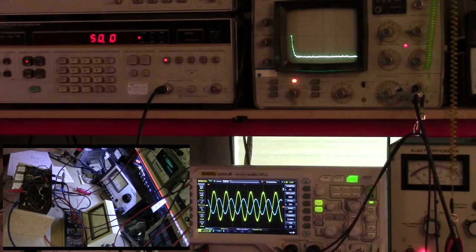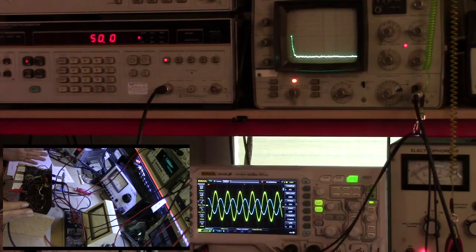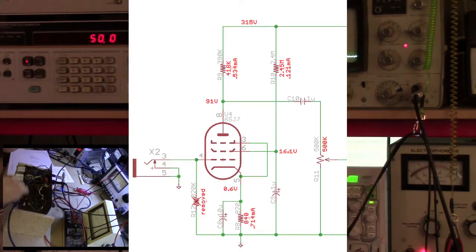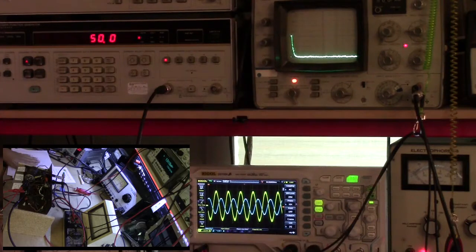It's fine for this amplifier because we're driving an 8-inch woofer, and we probably don't even want it to go that low. So we may end up modifying the cathode capacitor value to move that 3 dB pole up a little bit, so the 3 dB frequency is at 100 hertz or so. All right, let's keep going. So that's good.